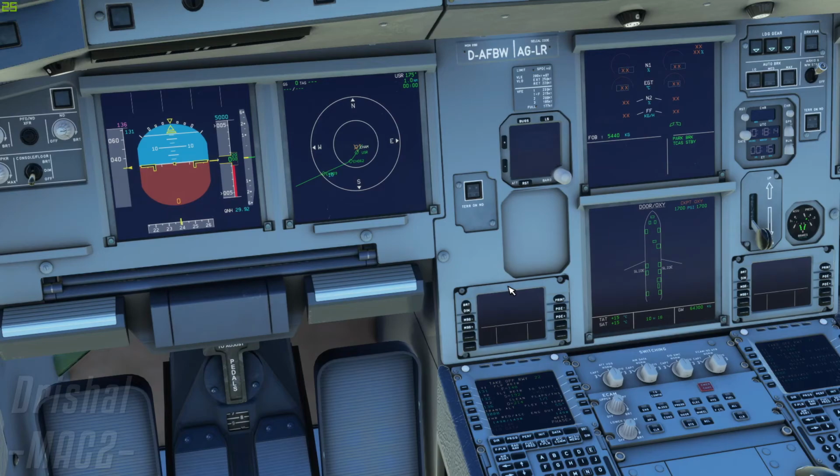VR is our rotate speed, so that is when we will pull up and the aircraft will take off at that speed. And V2 is our speed, which lets us know we're climbing, we're at good speed, and there's nothing, hopefully, seriously wrong with the aircraft. So they are important speeds.